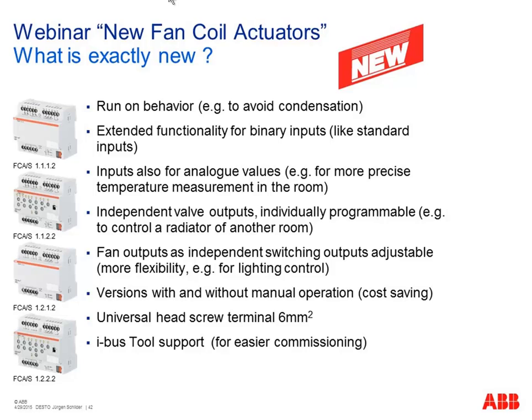And I think my last slide before Jürgen continues with the IBAS tool functionality, maybe the most important slide I showed to you today. If you keep this in mind, I'm already happy. What is exactly new with the new fan coil actuators? I have tried to summarize the main features here. Run-on behavior, remember: a new software feature to keep the fan running though the control value goes to 0.